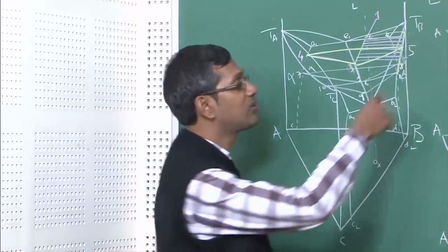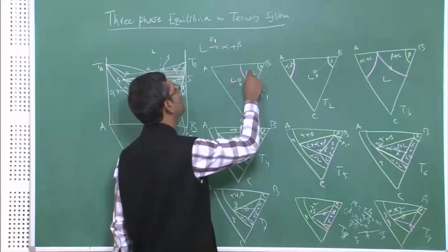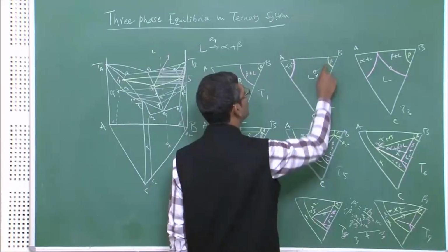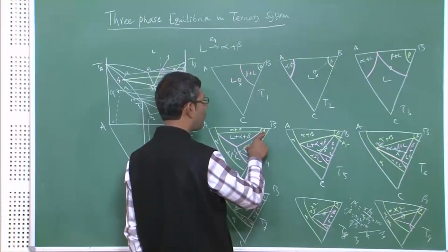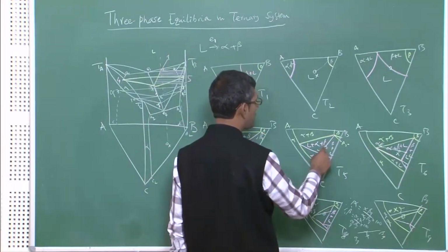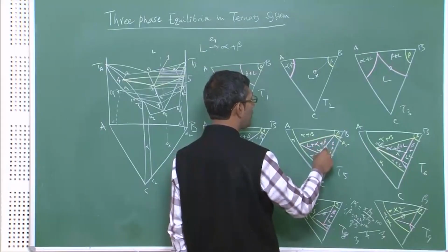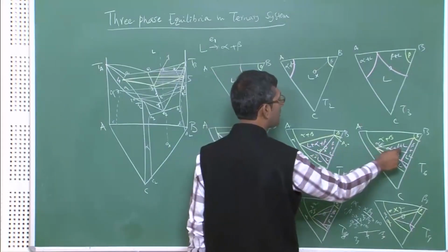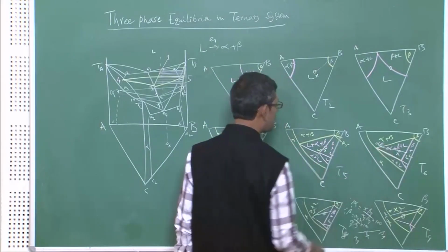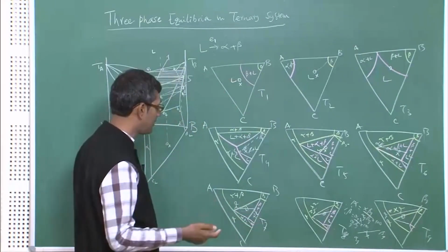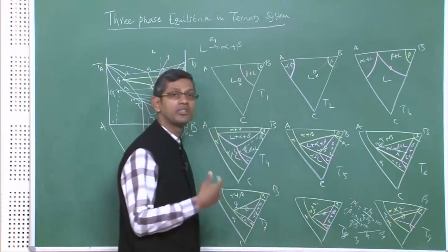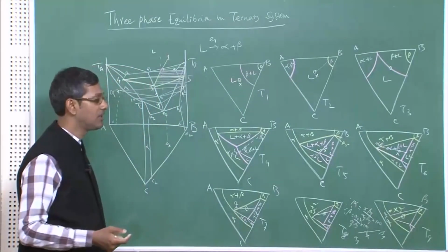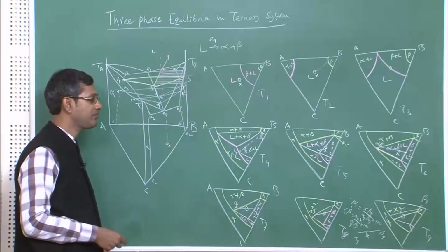Okay, so same thing is seen here, liquid initially, then liquid is in contact with beta, finally liquid and beta crystal, more and more beta crystal will form, then it will move into alpha plus beta plus liquid zone where alpha will precipitate, then more alpha will precipitate, more alpha means more eutectic, and finally it will move into alpha plus beta where the solidification will get over. That is how things will happen, and this is what you need to follow, correct.